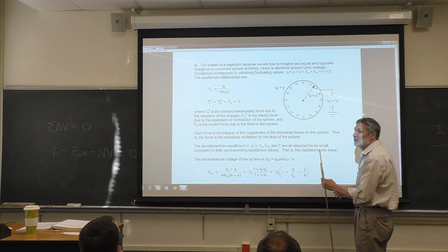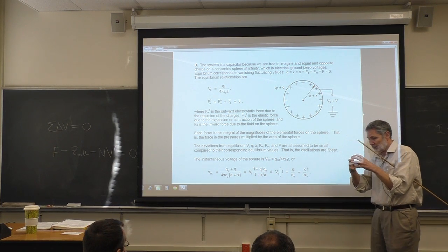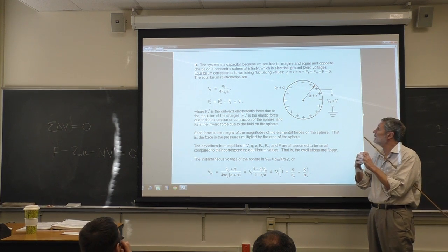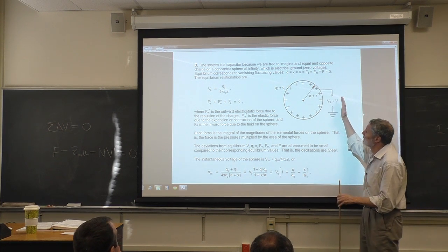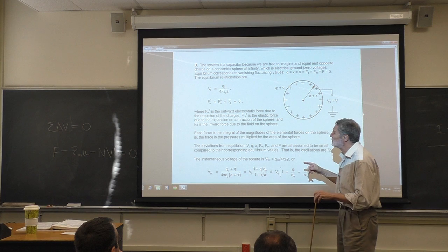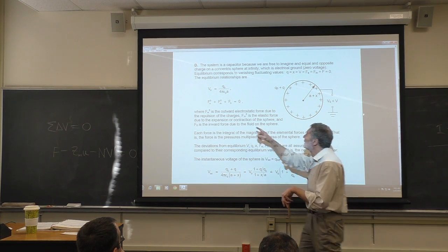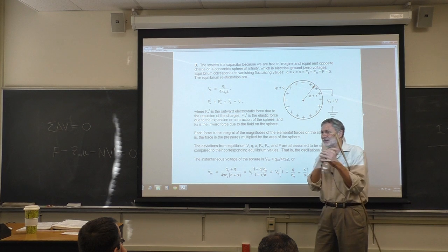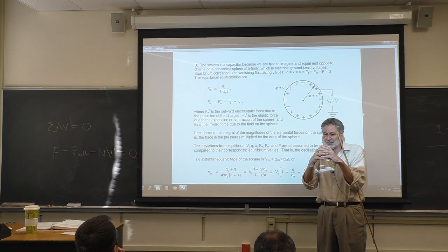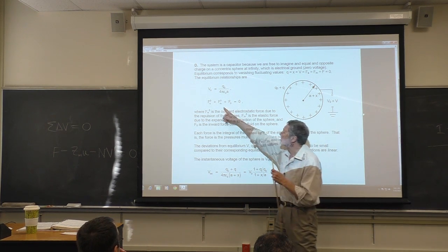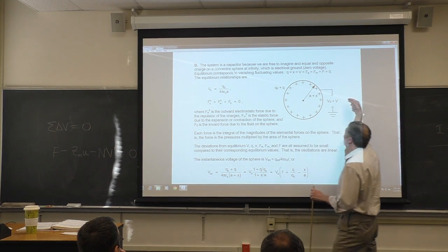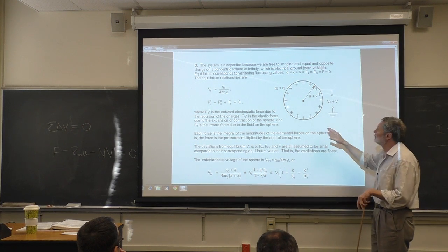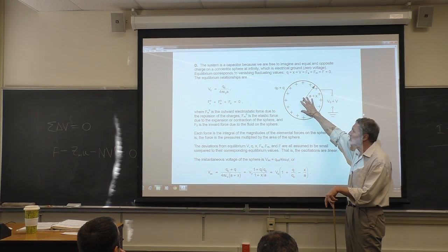So I can see two mechanical forces here. There's the stiffness of the material, the elastic stiffness, and then there's, excuse me, I see one mechanical force here. It's just the stiffness. This is going to have some stiffness. When you radially expand or contract, there's going to be a Hooke's law there for small oscillations, right? So that's this. This is going to be the force due to the fluid out here. And for simplicity, like I said, we're going to assume vacuum there.